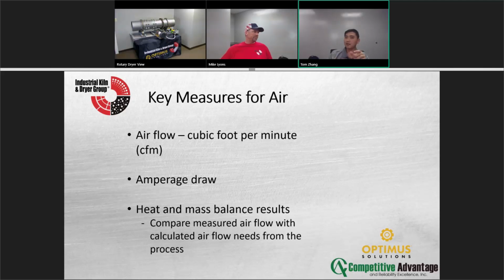Yes, and that's the thing: a process is typically very well balanced, and any little thing can upset it, and that's where the residence time comes back in on a kiln. On a kiln, if you make one change, and then another change, and another change, all within an hour, then you may have a whole slew of problems an hour later, because the stuff that you see in the beginning may not be the stuff that you see at the end. Right. Okay, so internals.